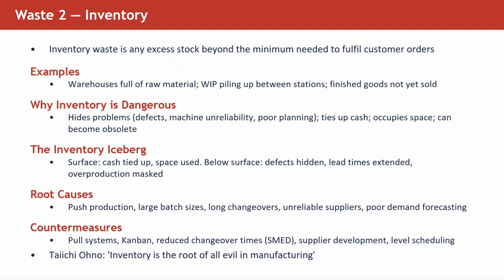Now, what are the countermeasures to avoid the inventory? First one, we need to go for a pull system, then go for Kanban. What is this Kanban? We'll see in the subsequent slides. Then reduce changeover times, usually known as Single Minute Exchange of Die, SMED. This is a very popular term in the industry, wherein we need to reduce the changeover times. As the name suggests, we have to keep it within a minute.